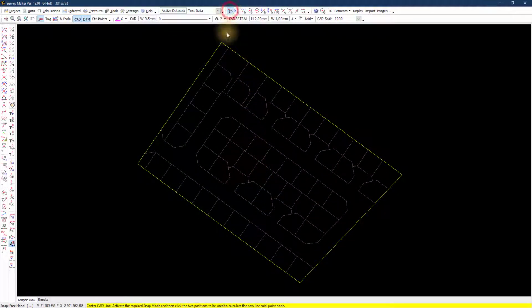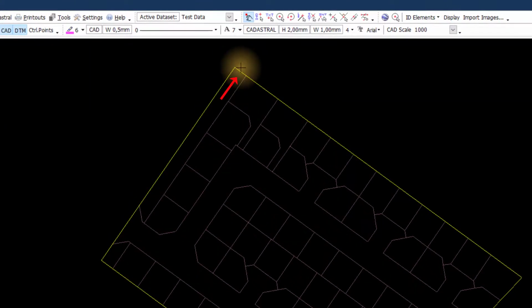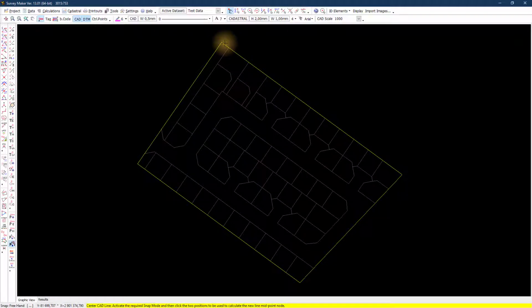Now it's important where you click when selecting the line. The cursor position next to the line will guide the function to either trace the polygon outside or inside. Clicking inside will trace the inside polygon. When you click outside, it will trace the outside polygon. You also will need to click close to the line endpoint of the first main figure point, from which you want to start the naming sequence.